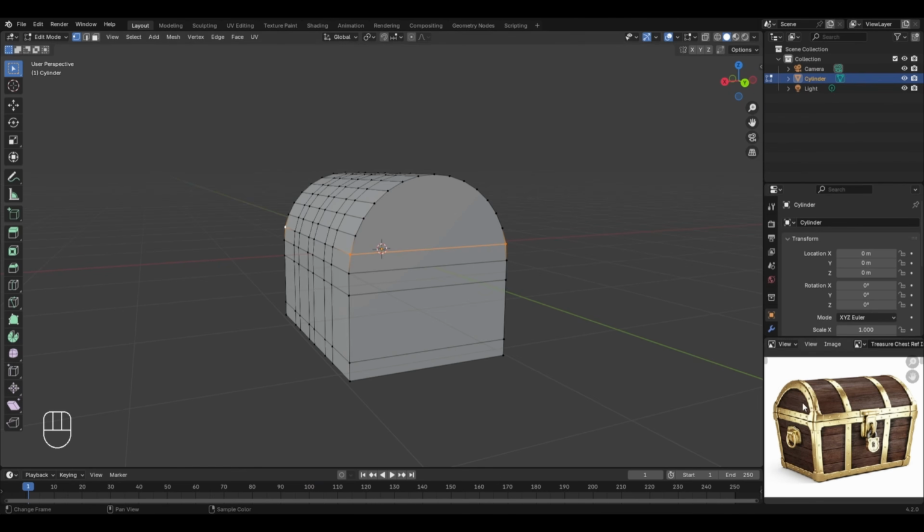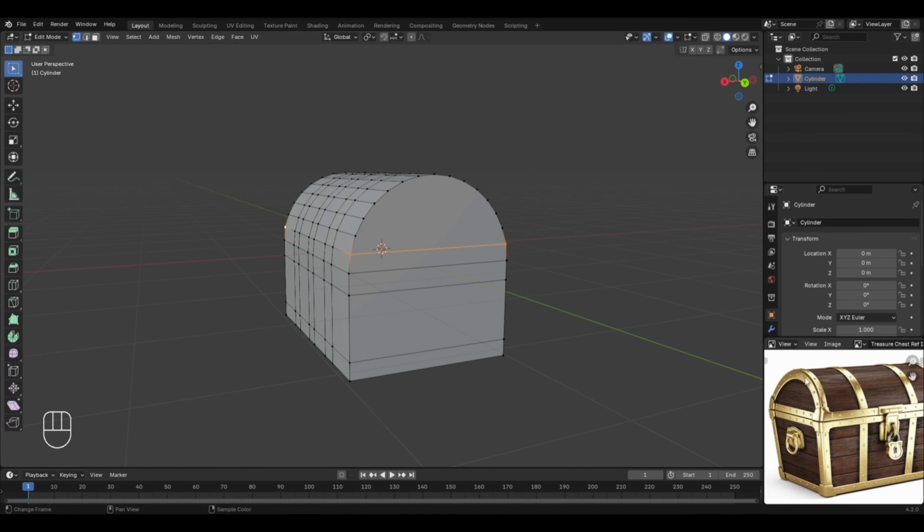Now the next thing that we'll do is to create the metallic cage on this side part. You can see in the reference image that we need to have some faces on the side part also in order to create the metallic cage. And for this, press 3 for the face select mode, then select these faces, press I to insert and left click to finalize. And with this, we are now having this particular face loop that we'll be using to create the structure of the metallic cage.